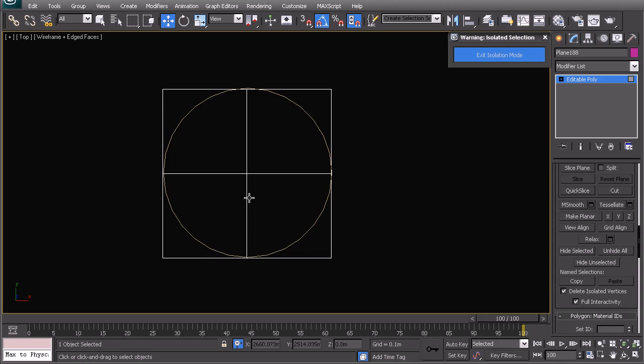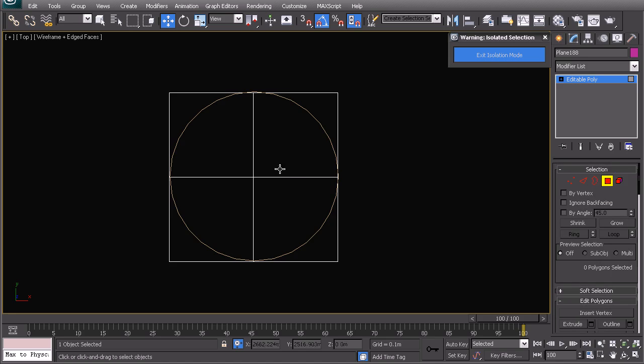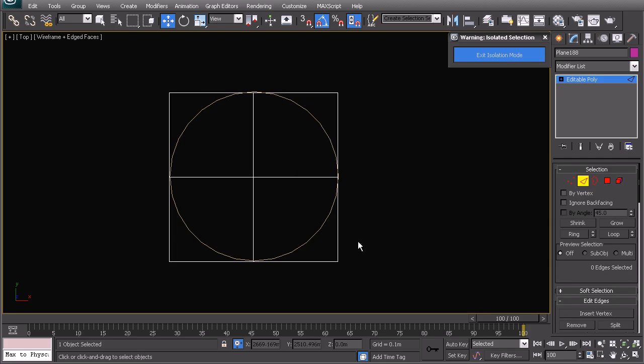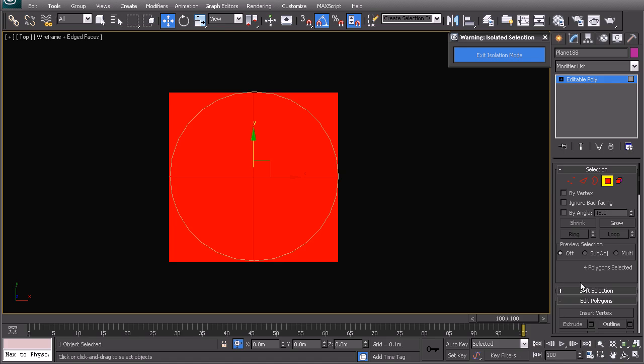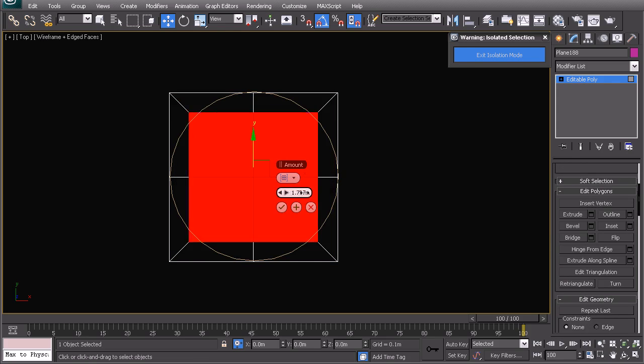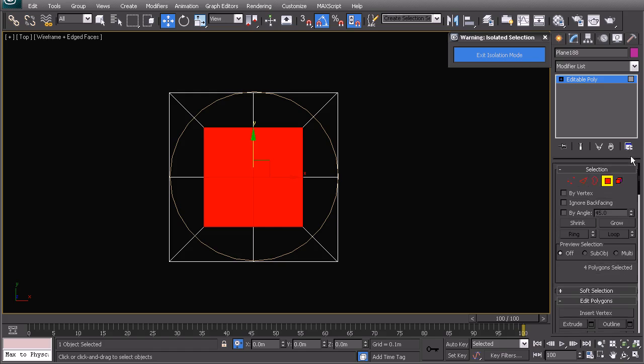We're going to subdivide it into 4, and then subdivide it one more time. This time let's do an insert, and we were just doing this process to get some more detail to it so that we can manipulate it later into this tensile structure form.